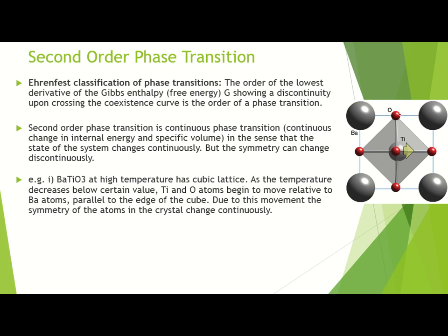You can understand that when you apply stress, there will be a change in the distances of the titanium and oxygen, and therefore the central symmetry which balances the charge will be disturbed. This material will become charged, or the part at the edges will be charged. That's how it develops the charge, and that's why it is a piezoelectric material as well.